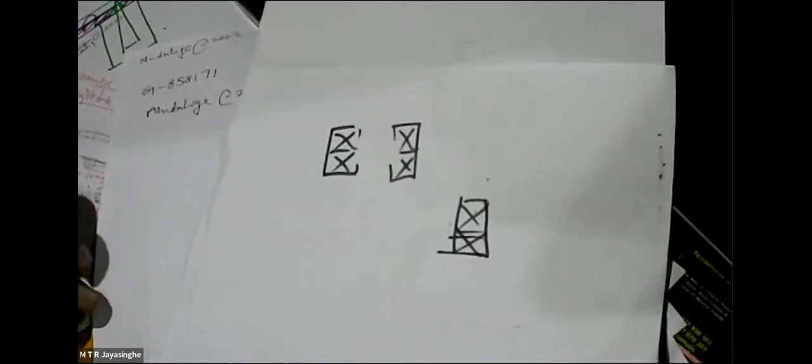Have some shear walls where you have the corner columns, and then you can fill it with masonry. Suitable strong block masonry would give you a reasonably strong shear wall, or shear core. But there's no need to use concrete everywhere. Select a reasonable number of shear walls, but ensure that the building is not twisting, as I explained last time. So it's the important point.